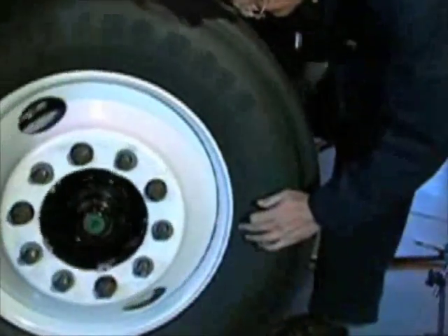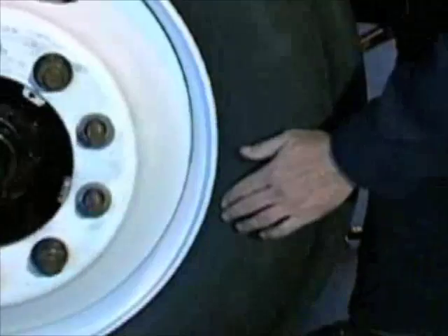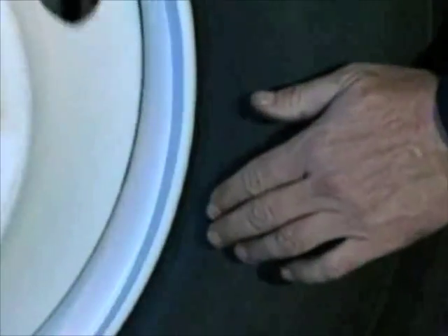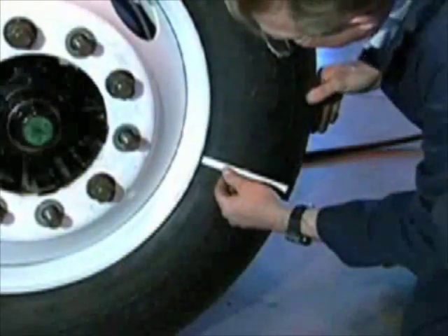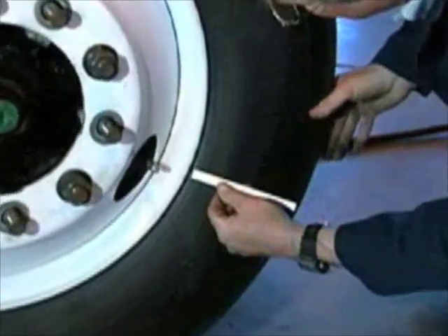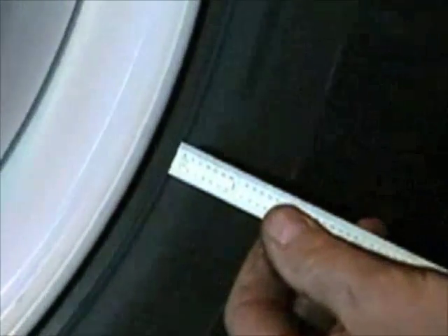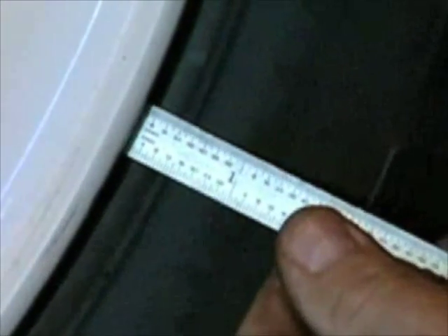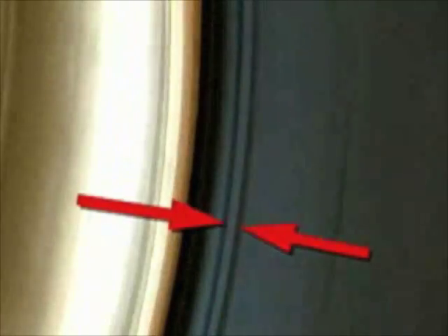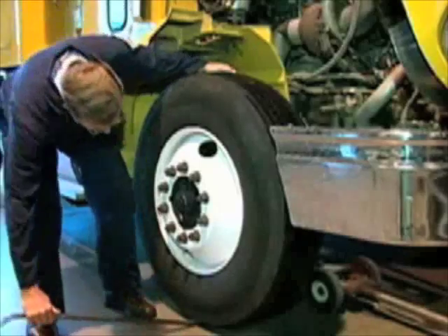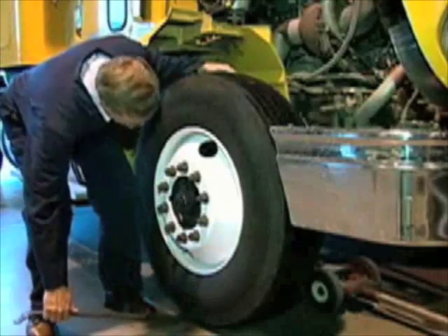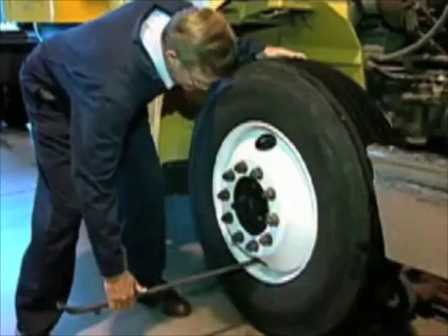Next, rotate the tire and inspect the guide rib area on the inside and outside sidewall area. If you see greater than a 2/32 variation in the guide rib distance to the wheel or rim flange area, it may indicate that the tire's bead areas have not been properly seated on the wheel. If it is not properly seated, mark the tire sidewall in crayon at the position where the guide rib area shows the greatest variation.